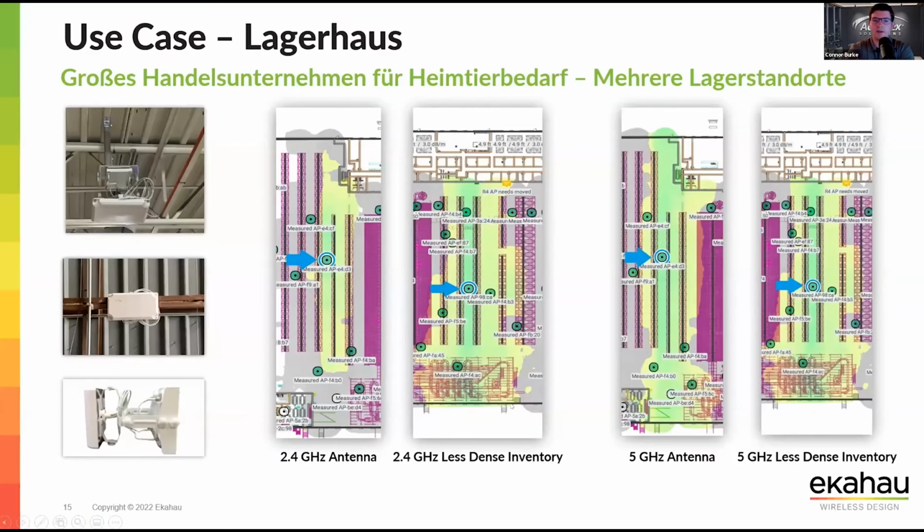So beginning with the warehouse, we see a lot of need for having a very directional antenna that goes up and down the warehouse aisles, because you can tell from the 2 images, depending on what inventory level or what your inventory actually is, can drastically affect how the antenna propagates, because it either can or can't go through that product, and it will attenuate the signal going through it or not attenuate it, and then you have bleed over into adjacent aisles.